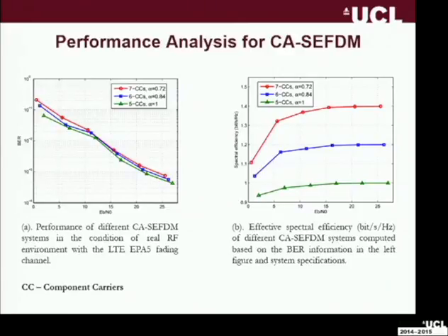Whereas typical OFDM is 1 bit per hertz, you can increase it to 1.4 bit per hertz if you have an alpha of 0.72. The reason it's almost 40% higher is because the actual increase in spectral efficiency is not 1 minus alpha, it's 1 over alpha. If you were to do the calculations, you would understand why. So here we got about a 38% increase in performance for the same SNR.